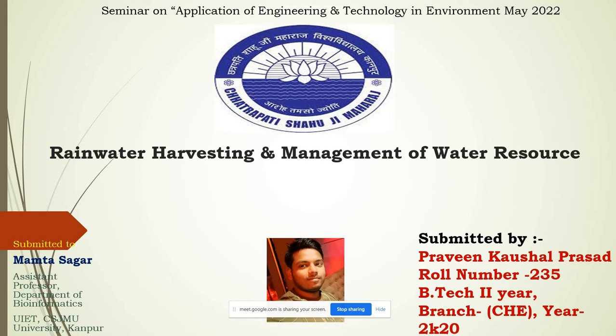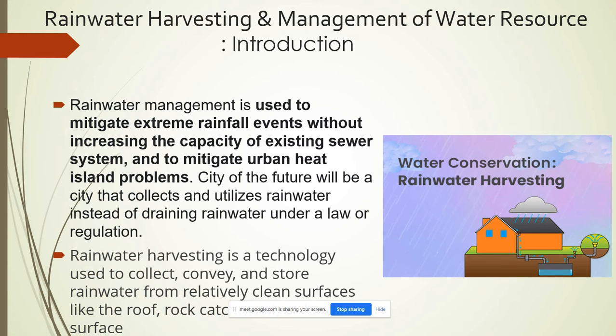There are some methods like water butt, direct pumped, indirect pumped, indirect gravity, gravity only, retention ponds, and in-ground storage. These are some pictures of in-ground storage and water butt applications. A water butt collects rainwater in a container from natural rainfall and or drain pipes. Direct pump is divided into two categories, submersible and suction.